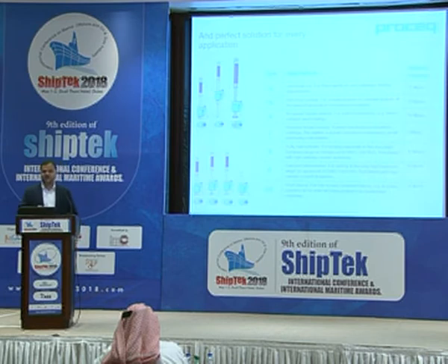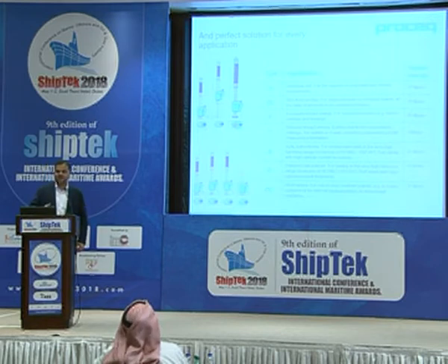And it's a perfect solution for different applications, because there are so many different applications. We are talking about the D unit, which is more universal, but DL is the slim foot version for restricted areas and to test at the base of grooves. G is good for heavy components, for heavy castings and forgings. And C is mostly for surface hardened components with lower impact energy or with a coating, so we don't damage the coating or the test surface. And S and E are for extremely hard materials, high carbon content, like tool steels and tool steels with high carbon content inclusions basically. E has a diamond indenter again, and the DC is the short device which is used more commonly for testing the hardness on the inner side of tubes and components.